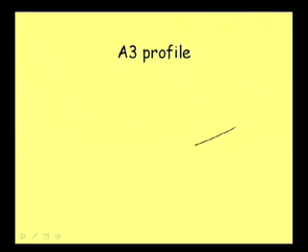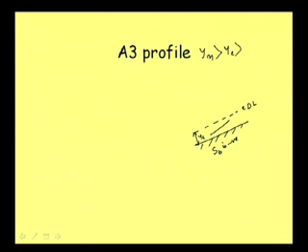In the A3 profile, you can write that SB is negative, this is our CDL line, and then the A3 profile will be a rising profile like this, because this is YC and the combination we have is YN is greater than YC and YC is greater than Y, and from this relation dy dx is equal to SB minus SF divided by 1 minus YC by Y whole cube. This is again for a wide rectangular channel.